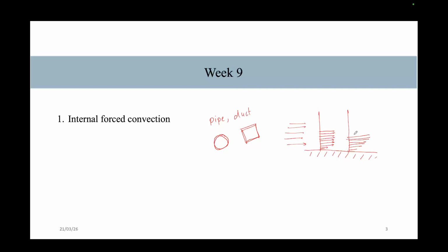So, like this way, and after that it will remain fixed. So that type of phenomenon. So you see, if I draw a boundary layer, you will find I'm using another color. If you draw a boundary layer, at this point you see the velocity is almost reaching the maximum value. Similarly, at this point it is reaching like this, and after that it is getting constant. So this is known as the hydraulic boundary layer.